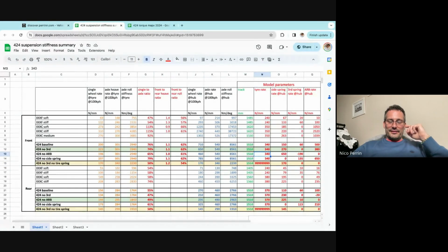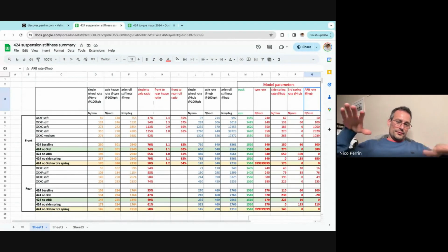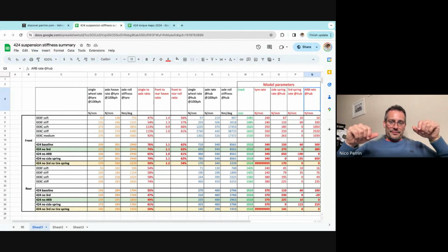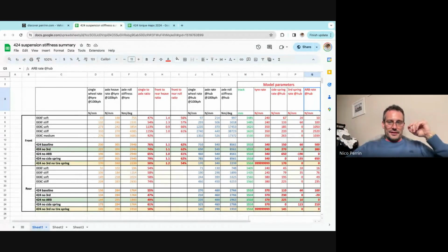Yes, thanks for the question. So what you're saying is that to do roll stiffness, you're right. We've got some side springs which are defined in this column, and the anti-roll bar will act. Both of them will act. We could have only one anti-roll bar to do the roll stiffness, or we could have only side springs. But then the side springs also act in heave, vertical. So you see, actually, we've got three options here.